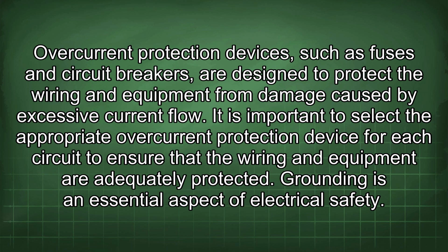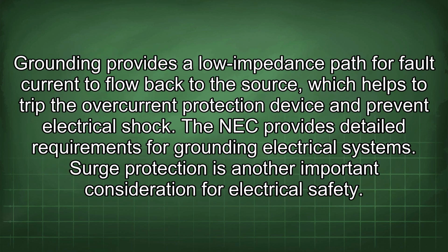Grounding is an essential aspect of electrical safety. Grounding provides a low impedance path for fault current to flow back to the source, which helps to trip the overcurrent protection device and prevent electrical shock. The NEC provides detailed requirements for grounding electrical systems.